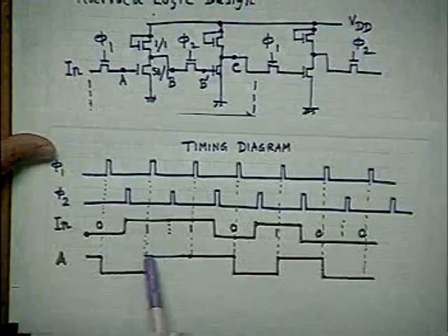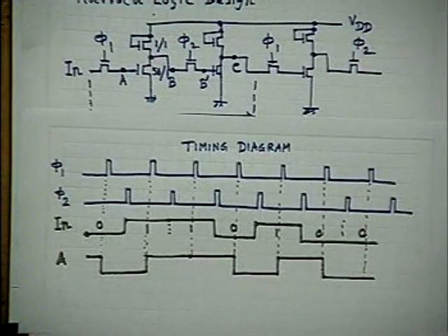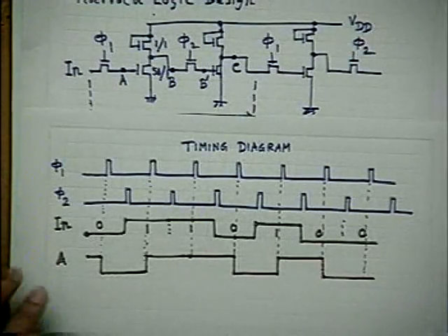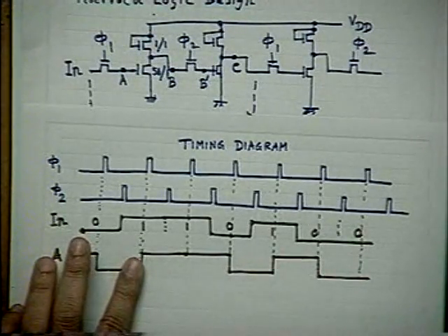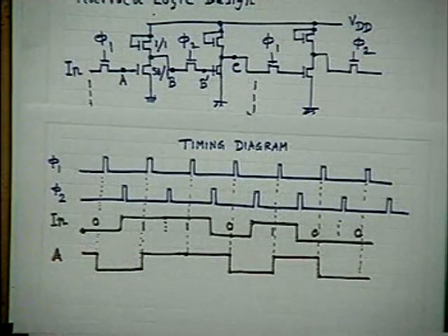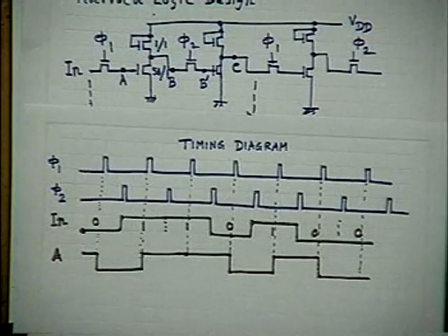Do you think that these lines will be perfectly horizontal? No. They are discharging, but with a very, very large value of RC time constant. Actually speaking, this is an exponential decay. But this time is so short compared to that RC involved that I am practically getting it horizontal. And that I want.